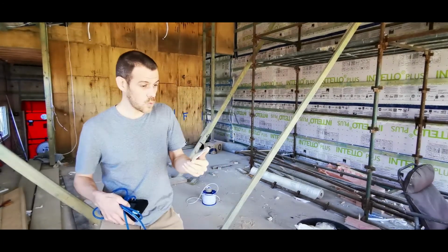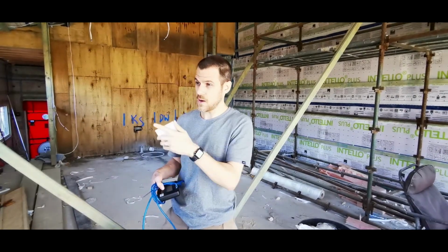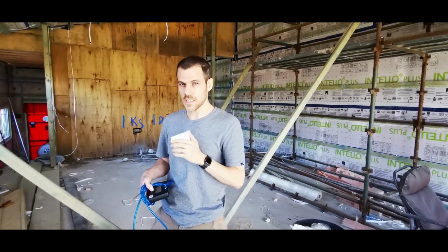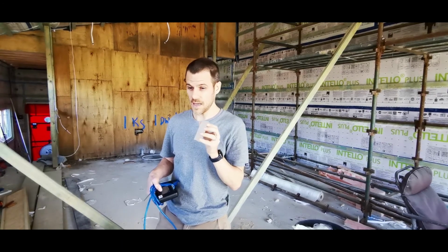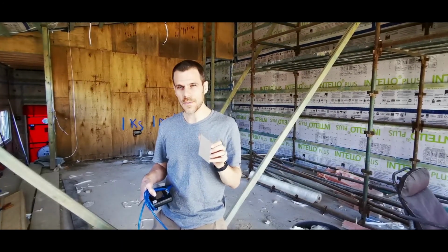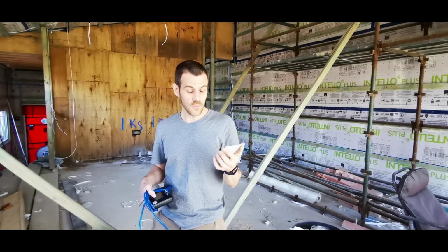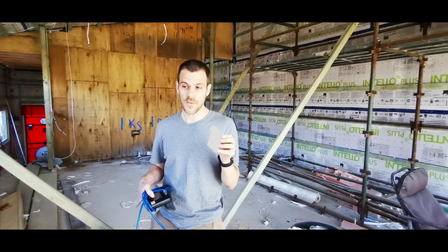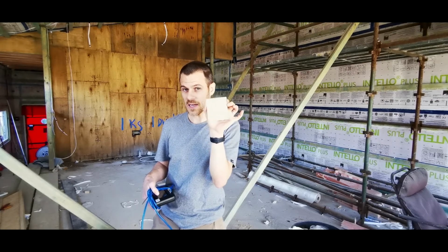As you're walking around looking for leaks, you have to think, okay, there's a little sliver right there. What's the leakage through that? There's a little electrical penetration there. What's that worth? You just start adding it up and remind yourself that all of those little leaks you find have to fit in this little box.